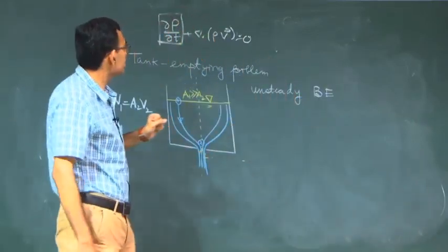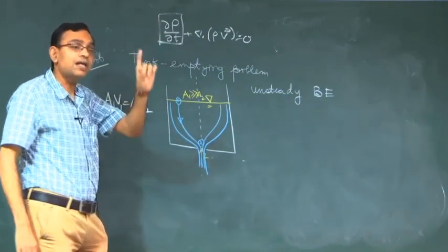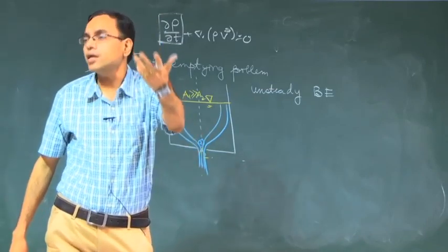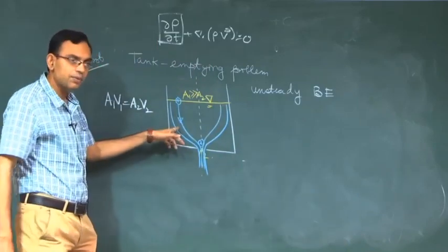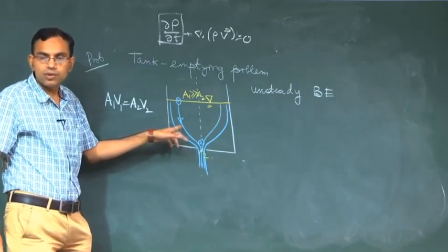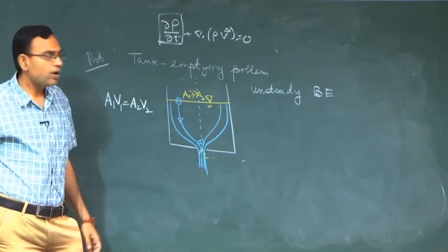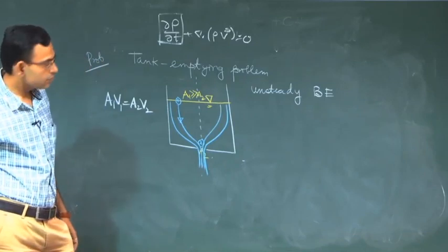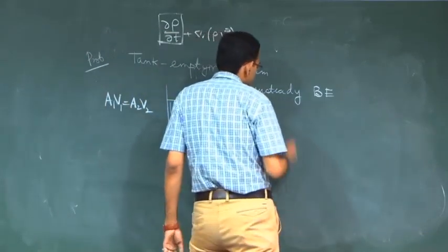The other, clearer case is where rho is constant but it may be unsteady flow, because although rho is constant, velocity may be varying with time, which makes it an unsteady flow. So this is such an example: rho constant but unsteady flow. When you have rho constant but unsteady flow, you have A1 V1 equal to A2 V2. Then let us write the unsteady Bernoulli's equation, which is more important.